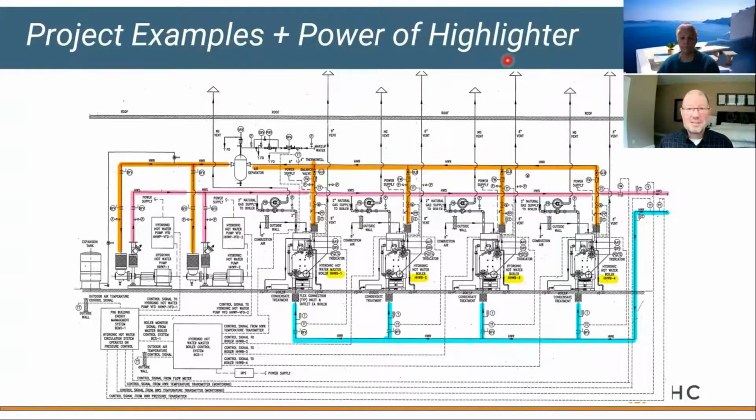Every time we have a trouble situation, the first thing I ask for is a flow schematic. Let's see what's happening. Put yourself in the pipe. Your cold water is coming back from the system. Hot water return. Okay, that's cold water. And where are we flowing? Oh, look at that. We're going below grade. Okay, that's interesting. Then we flow in here through our first boiler, which we call boiler 4, but we're also manifolded into 3, 2, and boiler 1.